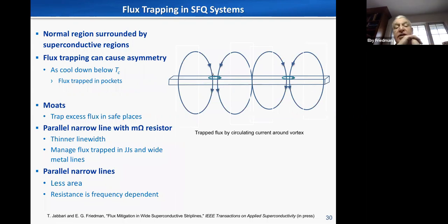So along those lines, there's another concept which I want to bring up. It's called flux trapping. You can literally think of antenna effects in CMOS. It's the same idea, where you have a piece of metal that can trap a magnetic field and disturb that state. And so then you pull the magnetic field from the loop and you lose a state, or you can add a state.